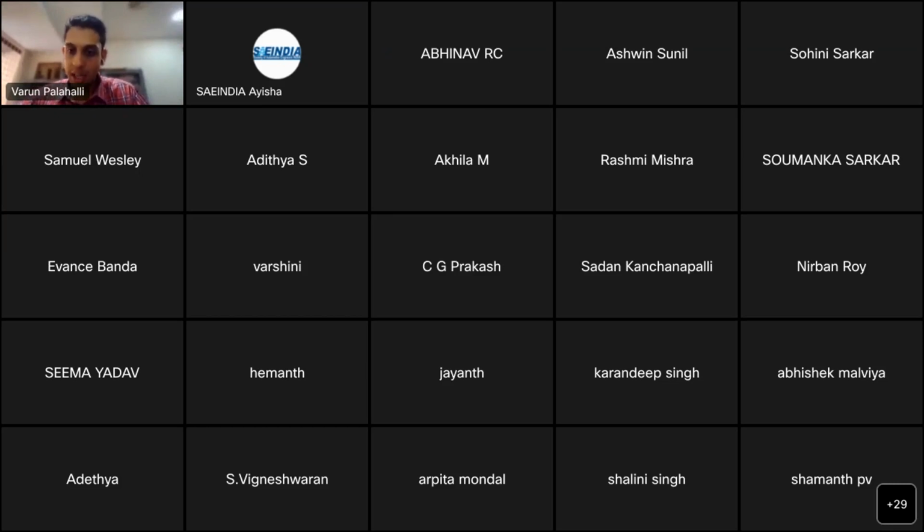Okay, Nakul has another question. So difference between normal mode analysis and frequency response. That's an excellent question. So normal modes analysis, you don't have any excitation load and you don't have any damping. So when you take a generic vibration equation, mx double dot plus cx dot plus kx equal to f, when you remove that c term and when you remove that f term, you'll be left with mx double dot plus kx equal to 0, and you solve that analysis as an eigenvalue problem. So you transform it into the matrix.